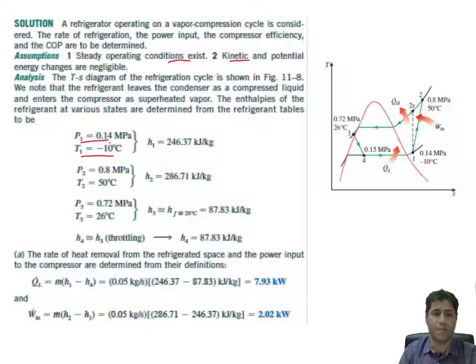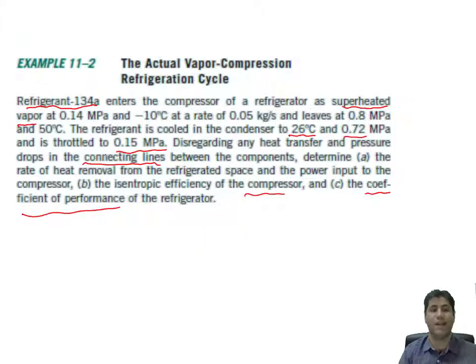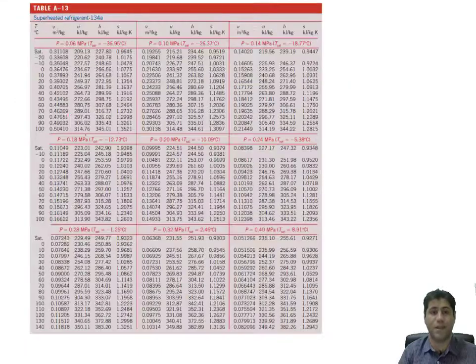In other words, P here is less than P saturation. So this state is in the superheated region. Now we need to refer to another table, the superheated region table, to find the enthalpy and entropy.